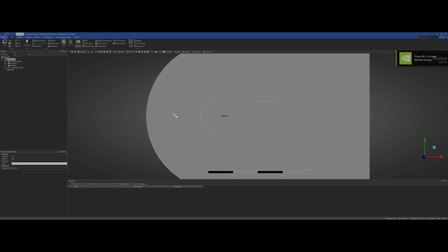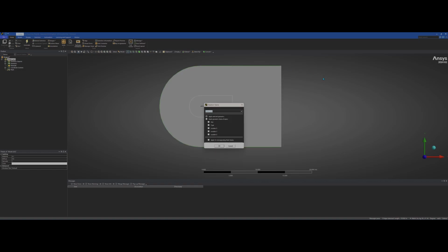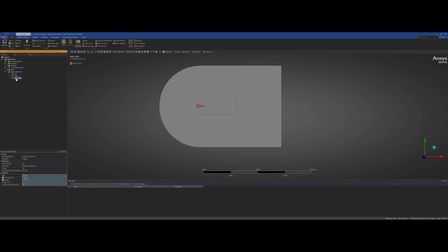Now here in the mesh, first thing I'm gonna do is name our boundaries. So I'm gonna name all the edges here, the outer ones, inlet. This one here will be our outlet, and then the airfoil will be our airfoil, NACA 4424. There you go. Yep, that looks good. Make sure they're all correct. You don't accidentally click a face. And yeah, now we could start with meshing.